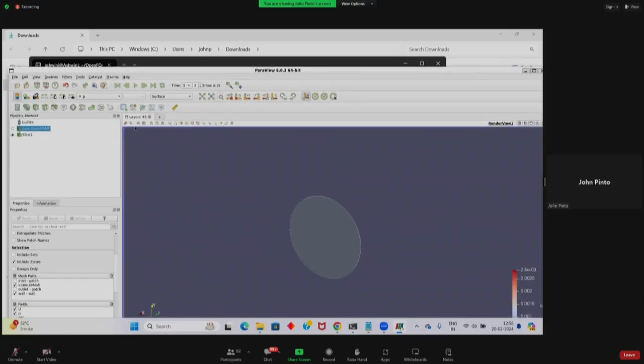I think Paraview should have those functionalities because Paraview can also be used to analyze data of other software. For OpenFOAM, this is data for the time instance of say 5. If I click this button, it will give me time instance 4. So all the time series data is automatically loaded in Paraview.